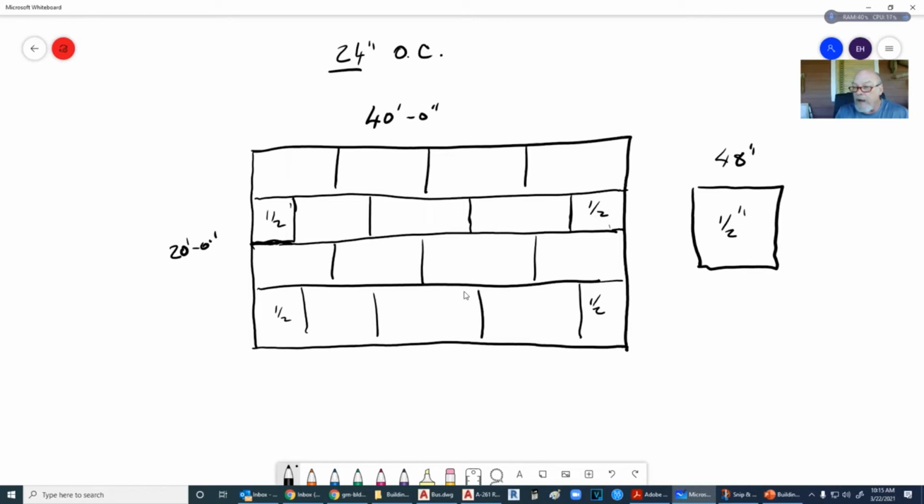So we're talking about 48 inches by 48 inches. And if we have to cut our plywood any more than that, then we're kind of spinning our wheels when we're talking about this. Well, the same is to be said about our roof as well. If we can design the house plan to have a perfect usage of the plywood here, then when we get to the roof and we design it so that it uses perfect sheets of plywood as well, then we don't have any waste.